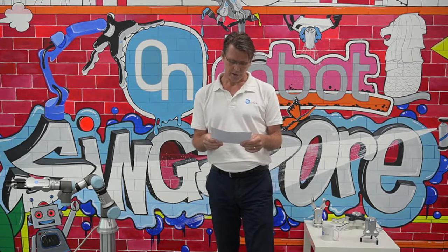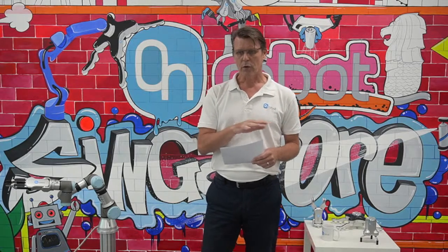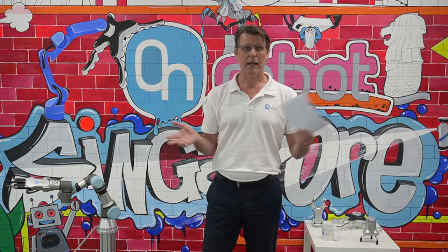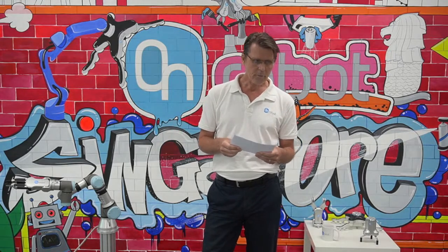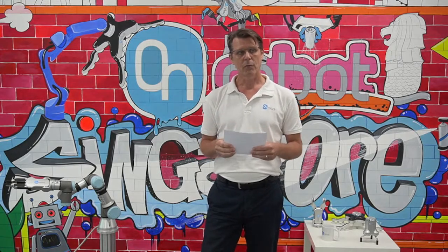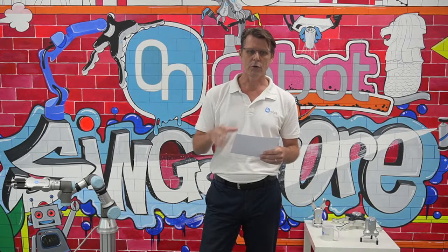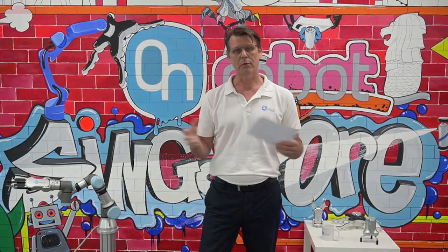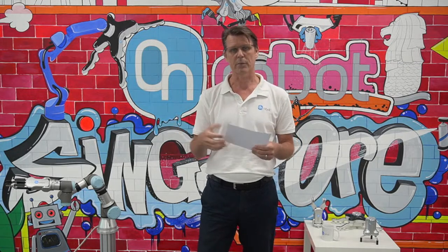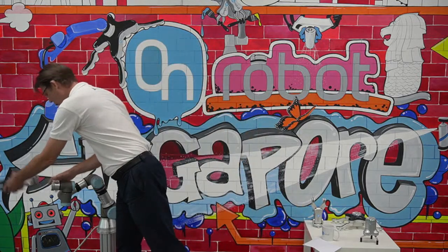Then I have another question. How do we know if a gripper is collaborative? Okay, so at the beginning of this session, I was talking about certain standards and specifications, ISO standards, right? If you go to the one I mentioned, ISO TS 15066, which is a specification, so it's not mandatory, but basically it guides you on what you should look out for if you want to have a fully collaborative automation, including a risk assessment and so on. As an example, talking about grippers, for instance.